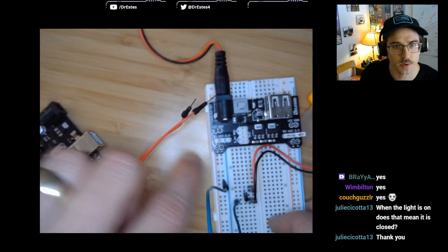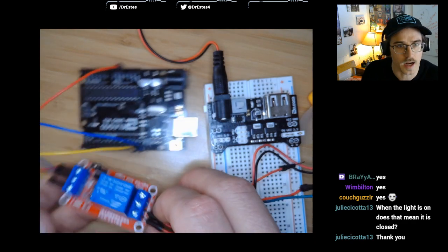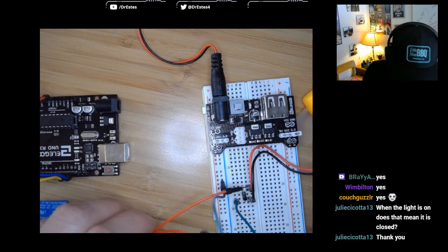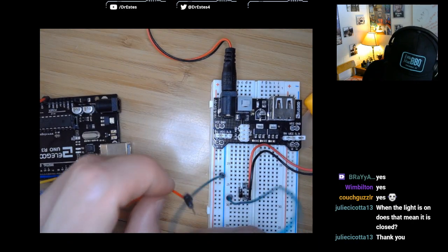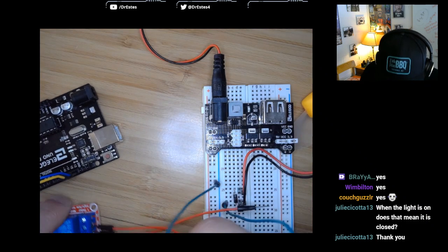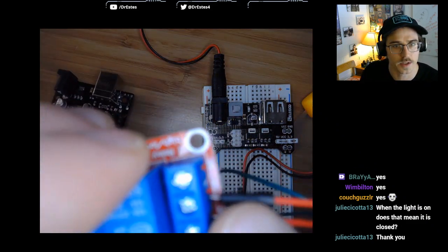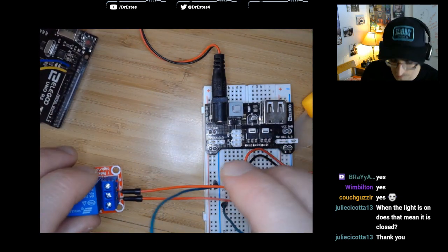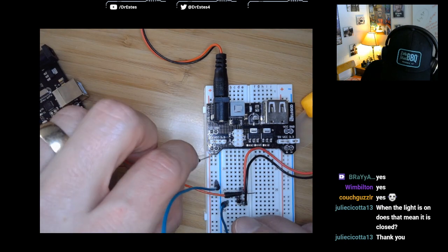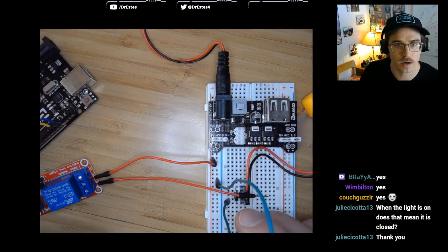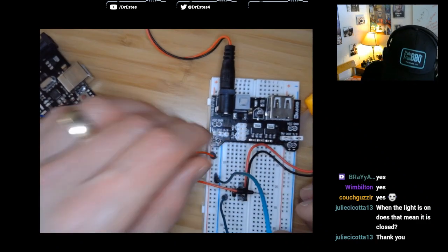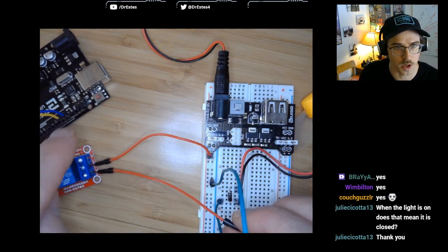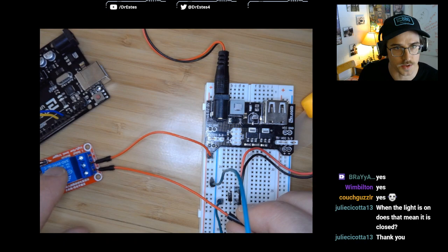So I'm going to take this 5 volt column and I'm going to send it into the relay first. So I'm going to take one of these. Actually, we should take the middle one, and on here, it's going to be hard to see. It says COM. Don't worry about it. But we'll take that middle one, connect it to the high power. So it's in that same column. And then, this channel is going to flow power to the motor as long as the circuit is closed.